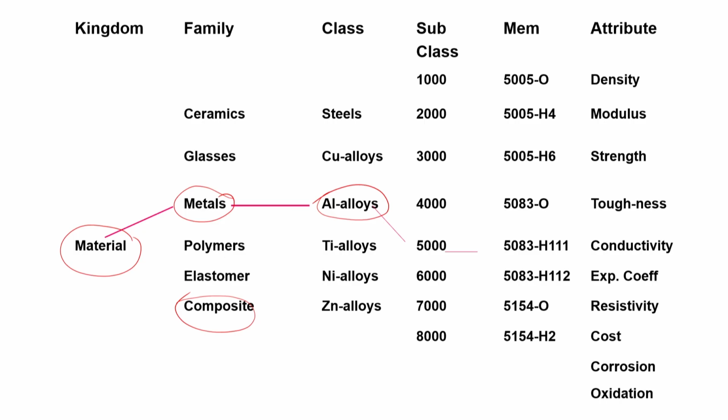Now, as I just now told you, aluminum has all these varieties in it. The variety that we will go for is the 5000 variety. Why? Because it is the 5000 variety which can be used in terms of a thinner skin and also is better in terms of corrosion properties, and it has a good strength.